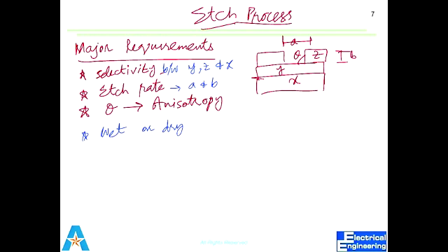Okay, so in the etch process, we have talked about all of these things. First of all, it should be selective. If X is the substrate, Y is the film that needs to be etched, and Z in that figure is the photoresist mask or any other mask it may be. So selectivity with respect to X, Y and Z, we call it the film to mask etch ratio, which means how selective it is to the film with respect to the mask.